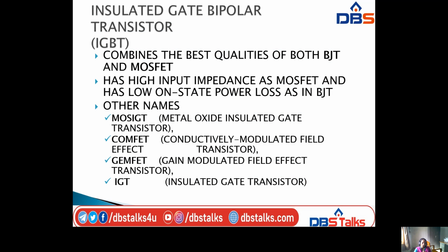And next, IGBT. IGBT means insulated gate bipolar transistor. It combines the best qualities of both BJT and MOSFET. It has high input impedance as in a MOSFET and a low on-state power loss as in a BJT.